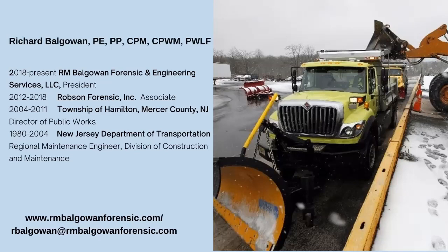There's a couple ways you can do that. One way is to have a pavement temperature forecast provided. If you have a weather service vendor that's providing forecast information to you, they can include a pavement temperature forecast in their forecast. And most of those entities have access to pavement sensor data. For example, New Jersey has at least 30 unmanned automated weather stations scattered around the state. And this is not including airports. This is just on the highway systems, monitoring pavement temperature, pavement condition, is it wet pavement, dry pavement, wind speed, wind direction, precipitation type and intensity. Often these things are referred to as part of an RWIS, or Road Weather Information System.